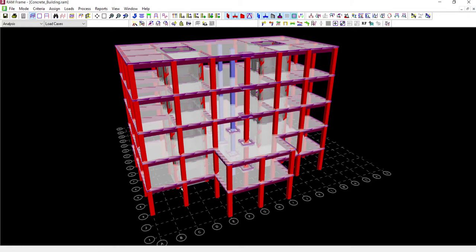And if we invoke the semi-rigid, that means the entire floor level would be meshed and a finite number of nodes would be created internally. So again, each of those nodes would carry its own degrees of freedom, for example, 3 degrees of freedom. If there are 100 nodes, then 100 multiplied by 3 would be 300 degrees of freedom for each floor level. So, why is it important?